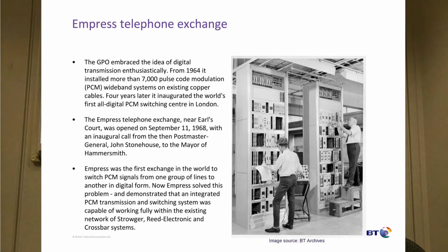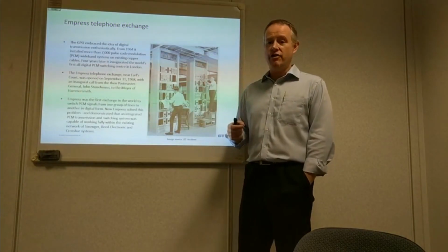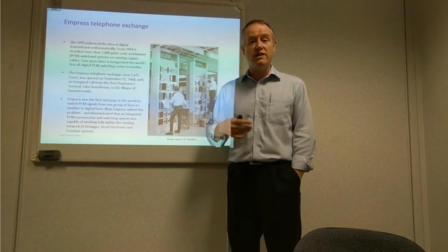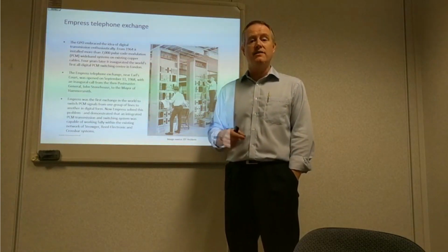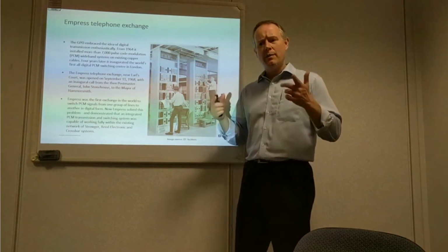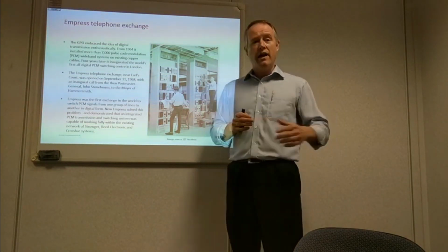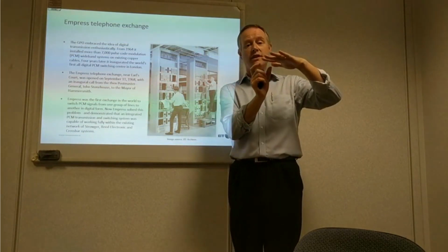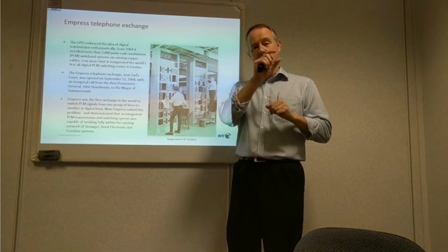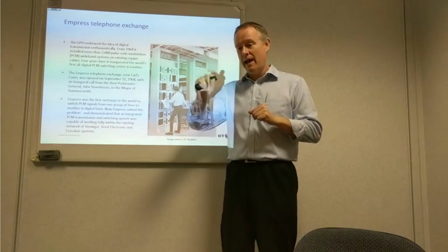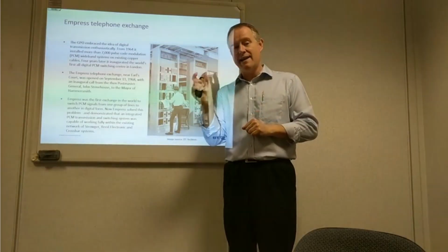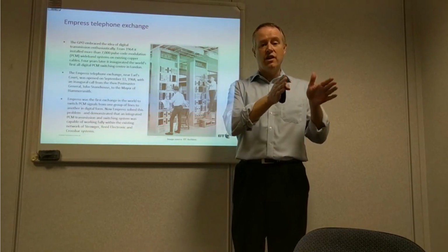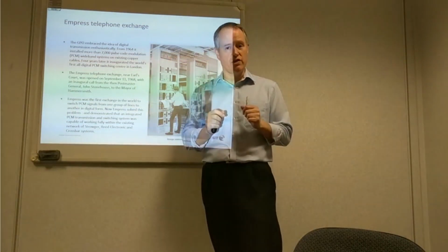But actually it wasn't long after the introduction of PCM transmission that we saw the introduction of the first digital PCM based switch. So now we start to think about a transmission line coming in that's carrying time slots. So you've got a little piece of information in one time slot that has to be cross-connected across a switch and leave on a transmission line at a designated time slot again. So you've got the need for synchronization not only in the transmission but across the switch as well.